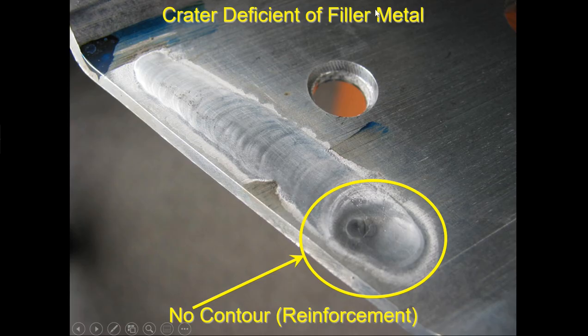Now this is 6061 aluminum. Now 6061 aluminum is, I'm going to say it again, metallurgical solution. So we had a problem one time where there were some cracks. And these cracks were starting to develop on the inside. And this was a key problem, because it broke rules. It broke rules in that the first rule is you don't put weld where weld is not supposed to be. And there were some cracks developed from the other side that actually put a little bit of a crack along here that would have said, scrap it.